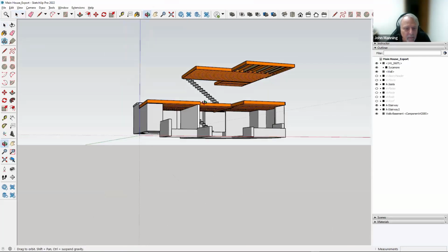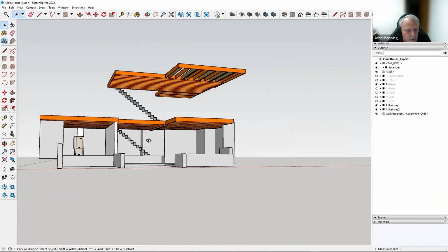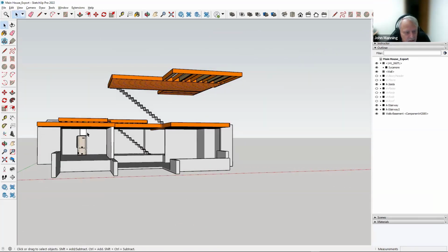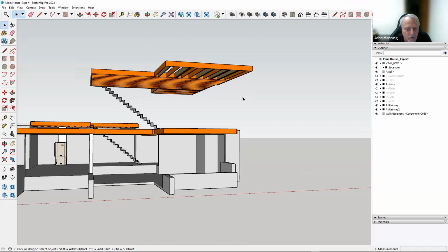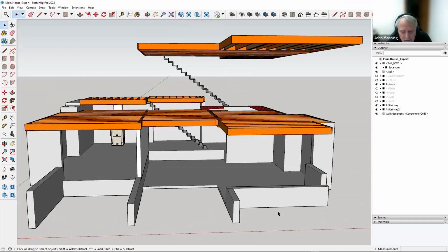And what I find the most challenging part is the way the floor joists interface with the support beams. And it's impossible to get air through that beam. So either we run a trunk down one side of the beam and build soffits. And if we were to go with a watered air solution, I feel the best location for the heat pump is back in the corner of this mechanical space. But with that, I guess I'd like to turn it over to perhaps Josh or Kevin to articulate a little more about the customer's needs and the space and the repercussions of a distribution system in the space.